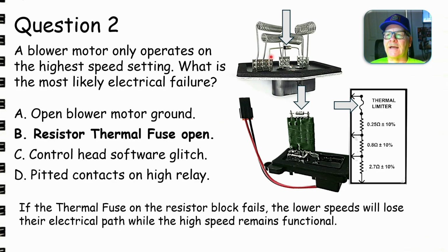But I'd come back and I'd put some dielectric grease and some alligator clips on here for heat sink to keep my soldering operation from opening the thermal fuse. And then I would clip out the old fuse, and I would solder in the new one.